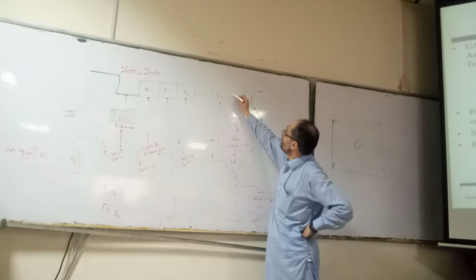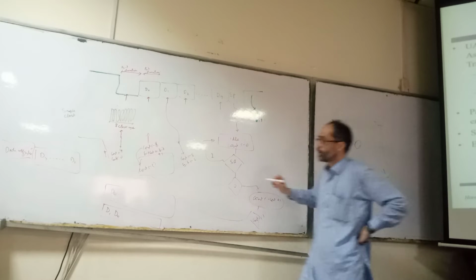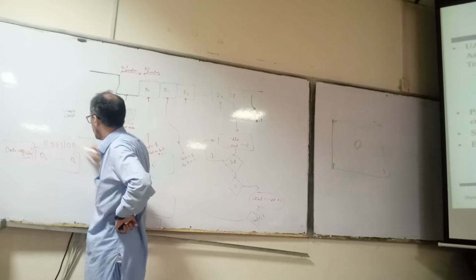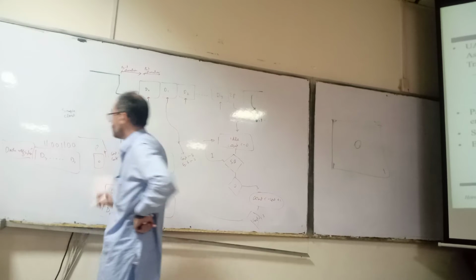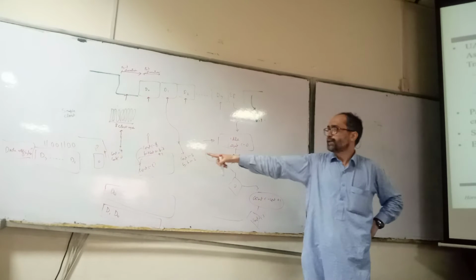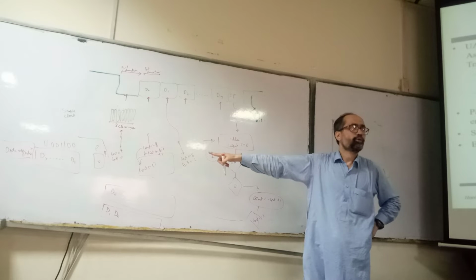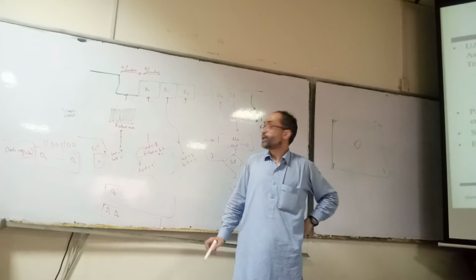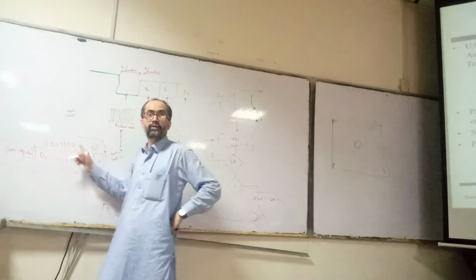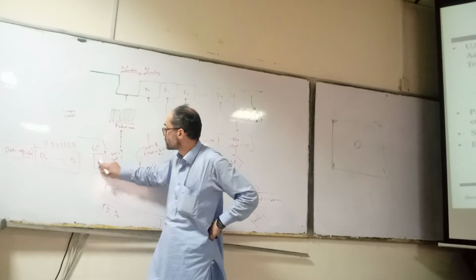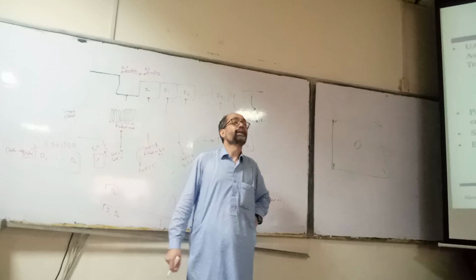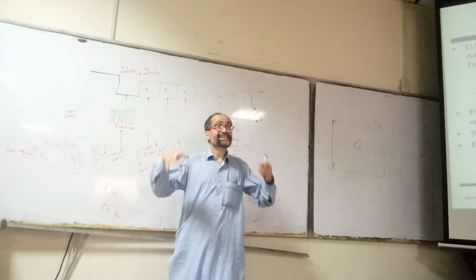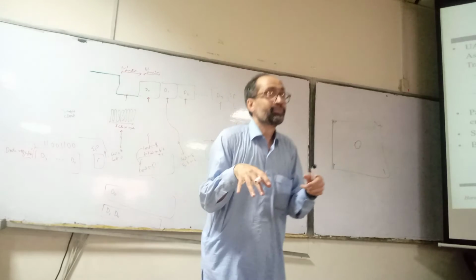So now let's assume it is even parity, and the data we have received is 1 1 0 0 1 1 0 0 and the parity bit is 0. Is there an error in the data or no error for even parity? No error, because the number of ones is even. But if the parity bit is 1, there will be an error.